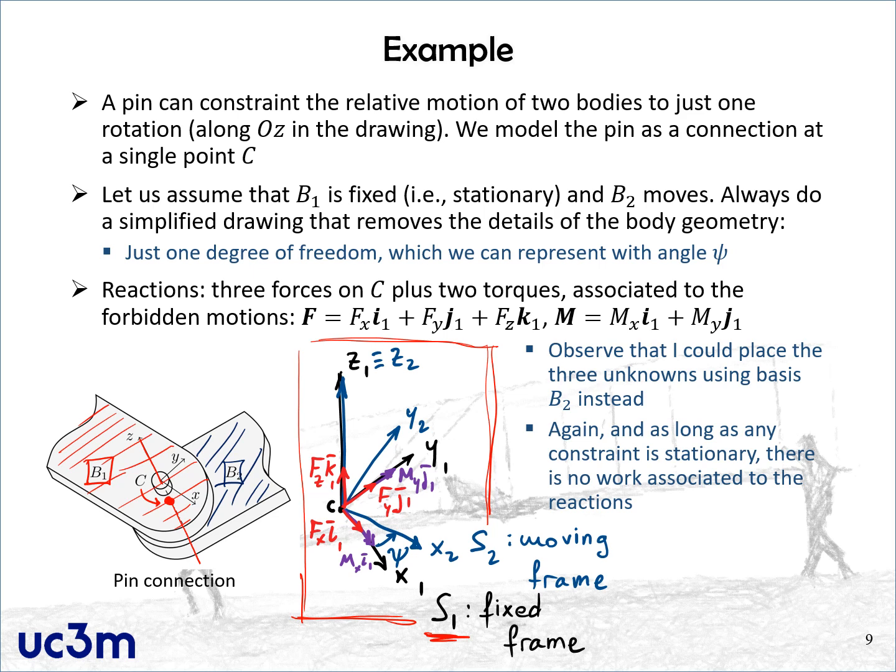These equations are the following. We just have to say that the components of the position vector of point C are all of them equal to 0. So these are the first 3 equations. On top of that, the constraint forbids the rotation about the x-axis and the y-axis. So we can also write omega x and omega y equal to 0.